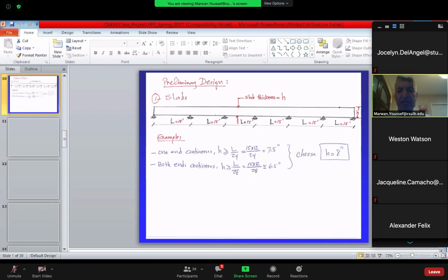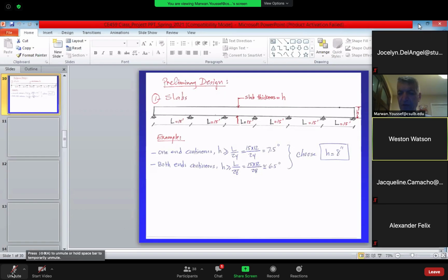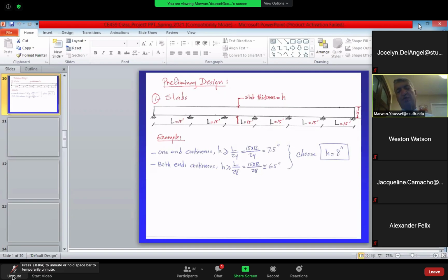So last time, very quickly, we talked about the cracking moment formula, how we get that. Right? We did do this, right? Anybody? I don't really remember doing a cracking moment formula. All right. So let's start from the cracking moment then. So we said that the beam is going to crack on the tension side, as you can see here. So we want to know what moment it takes to crack that beam, and that moment we're gonna call the cracking moment.